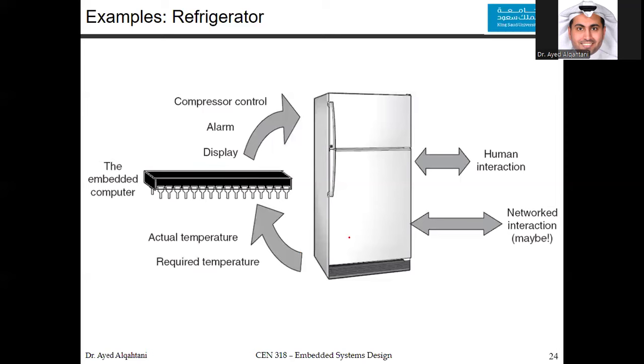We have also interrupts, which is an event that suspends the main program execution. It interrupts it while the event is served or handled by a program. This program is called the ISR, or the interrupt service routine. So the CPU would love to continue execution without any interruption. But sometimes you need these interrupts, usually from an I/O or from other modules, that tell you that a certain event happened.